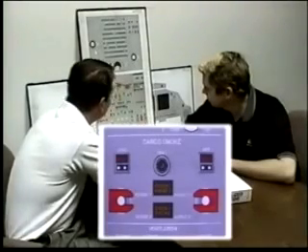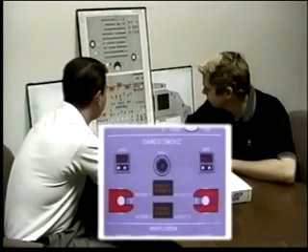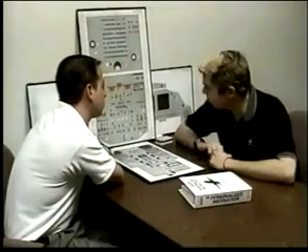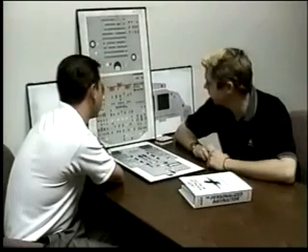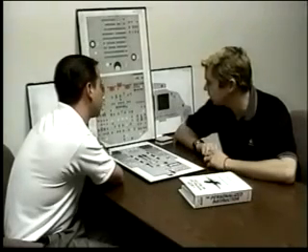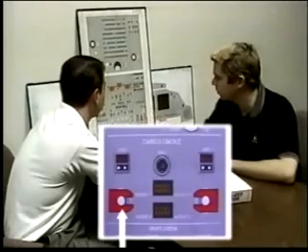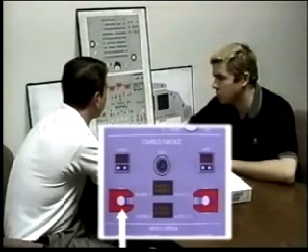And let's say you get smoke in the forward cargo compartment. Kind of walk me through what you're going to do. Well, I'm going to follow ECAM, and basically it's going to tell me to discharge agent 1 in the forward pit. So I'm going to lift the guard, and I'm going to move the switch to agent 1.